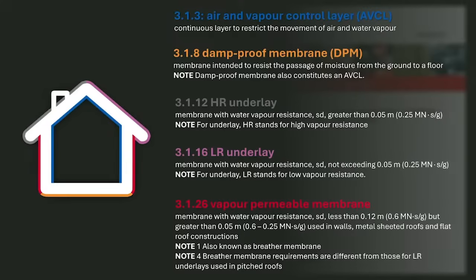LR roof underlays also provide temporary weather protection, but are also permeable to moisture vapour, which may allow the ventilation requirements to be reduced. Some LR underlays are air permeable as well as vapour permeable, and we'll discuss the effect of this later in the CPD.